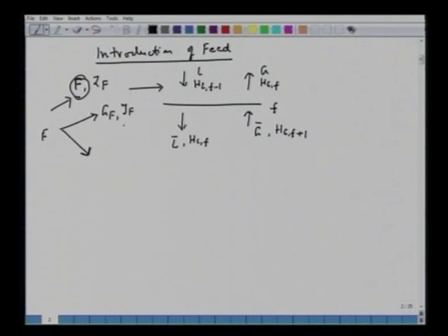So some vapor compositions, and we have HGF, specific enthalpy for this vapor phase, and it's a mixture of GF plus LF with XF, and we can have HLF. All right, so several combinations for feed is possible. Let's start with this general case where the feed consists of vapor as well as the liquid with the composition YF, XF, HGF, and HLF as specifications.